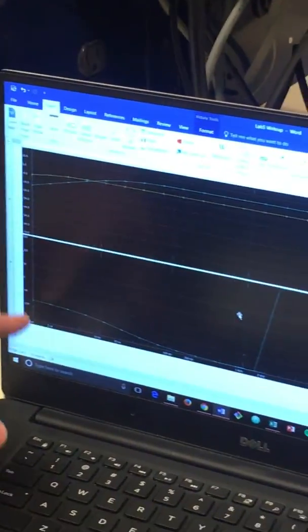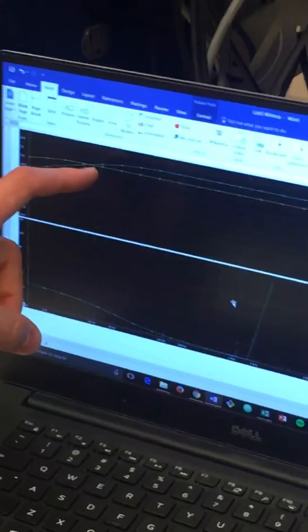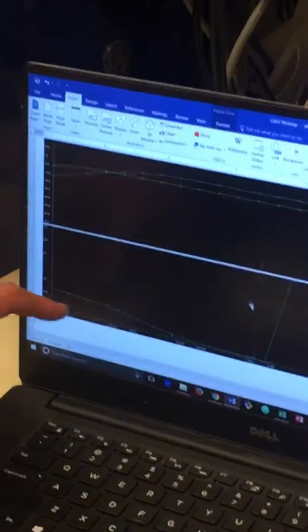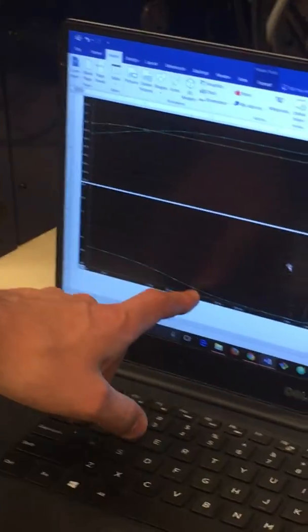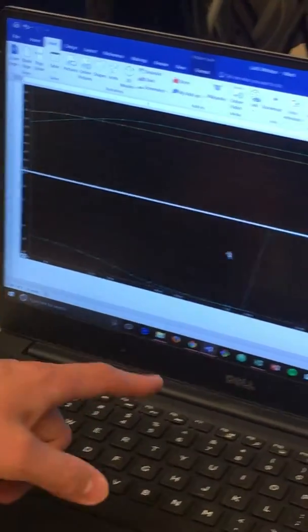So at low frequencies now, the signal is attenuated here. And then at high frequencies, you get the gain based on the maximum potential, which is the ratio of the resistors. And then the phase response here, it's kind of out of phase negative, and then in the middle it's completely out of phase negative 180, and then it switches to positive 180.